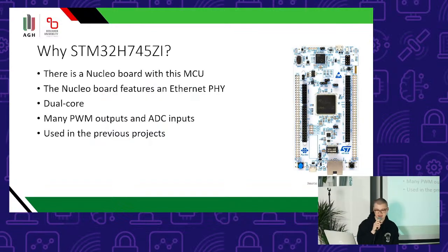Why this MCU, the STM32H745? Because there is a Nucleo board with this MCU. This Nucleo board has a built-in Ethernet PHY with an Ethernet connector, so that we can get rid of all the cable mess when we have external Ethernet modules, which introduce some voltage drops across the cables and some interference, and we don't want that.